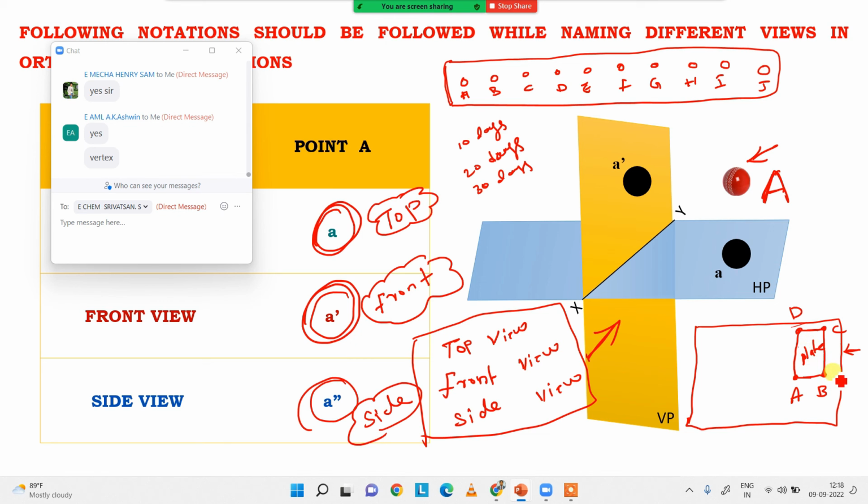We're telling, for example, this is height 10 millimeter, which is 5 millimeter. You need a rectangular plate. So you give names also. You mention A, B, C, D. Also you mention, you need the front view. I'll just put FV. This is the front view, and I also need the top view. How it looks from the top view.